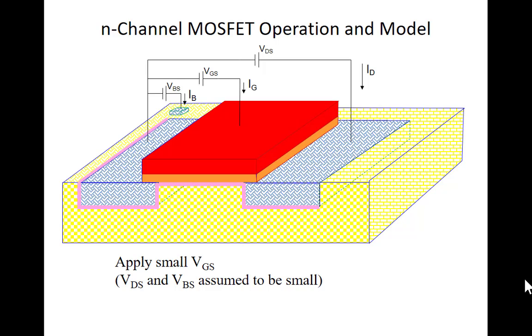If I put a positive voltage on the gate, I'm trying to pull electrons to the surface. And so what I'll do is I'll end up creating a depletion region underneath here, because it started out p-type, and I'll succeed in pulling some electrons near the surface, and that will ionize that region underneath the gate. There's no current that's going to flow because to get from here to here, we've got a reverse bias junction here, and we can't get through here either because there's just a depletion region there. So the drain current is going to be 0.